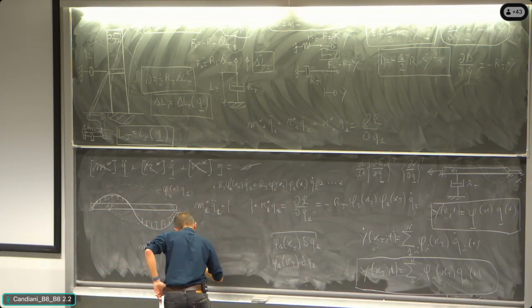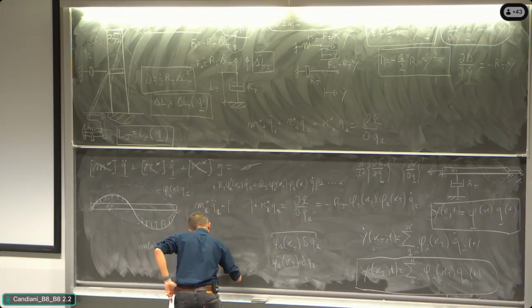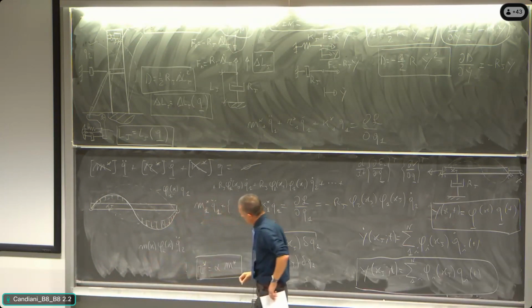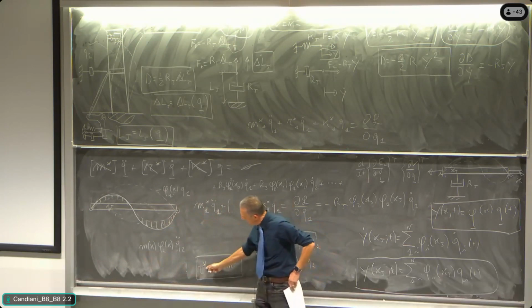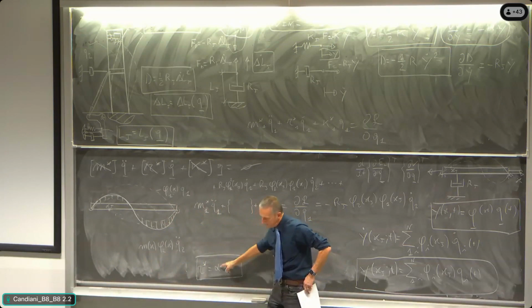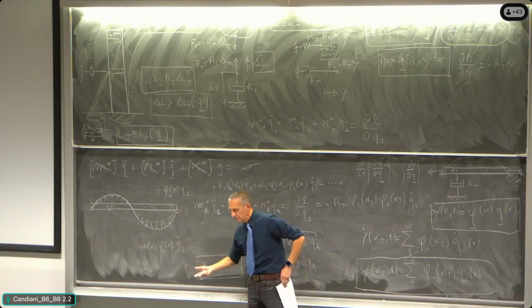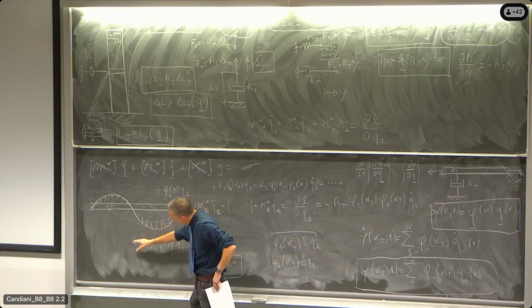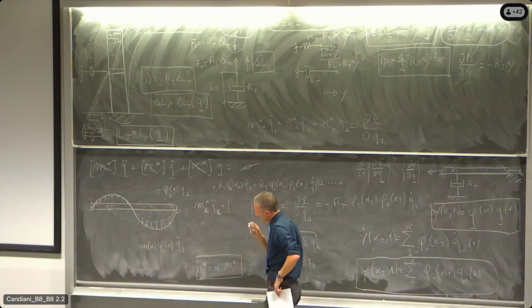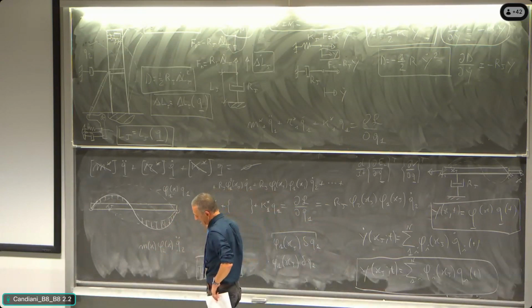But then the move from distributed mass to distributed damping will be simply to say that the contribution into the distributed damping is something that is alpha m star. So let's say that we are assuming that the modal damping is proportional to the modal mass. So we are making a similitude, and we do not go into more detail. So let's make the example on the distributed mass, and then we have an intuition of the distributed damping.